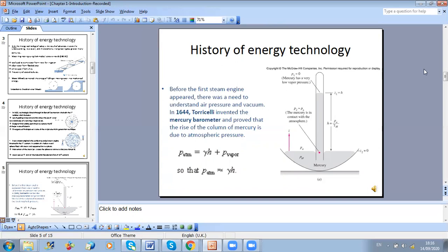So a flow of high pressure represents a high potential of energy, because if you reduce the pressure of this flow, then you can convert the flow energy into another type of energy, which can be potential or kinetic. As in the case of the first turbine of Fourneyron, it is turned into kinetic energy, and this kinetic energy will rotate the blades.